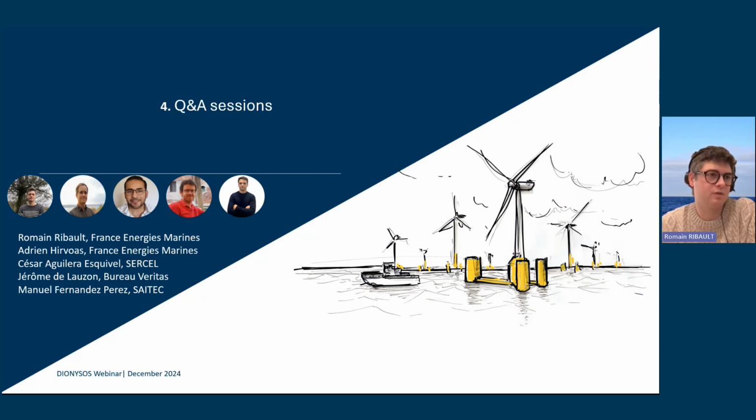So first one from Owen Pocock. Were any physical sensors, monitors placed on the mooring lines? If not, did you calibrate the digital twin response for the mooring lines? So on this, I can try to answer for both Zephyros and Demosat. For Zephyros, we didn't have very precise measurements from the mooring line ends, neither anchor positions, and so we did calibrate the length of the mooring lines to match the surge and sway natural frequency of the system.